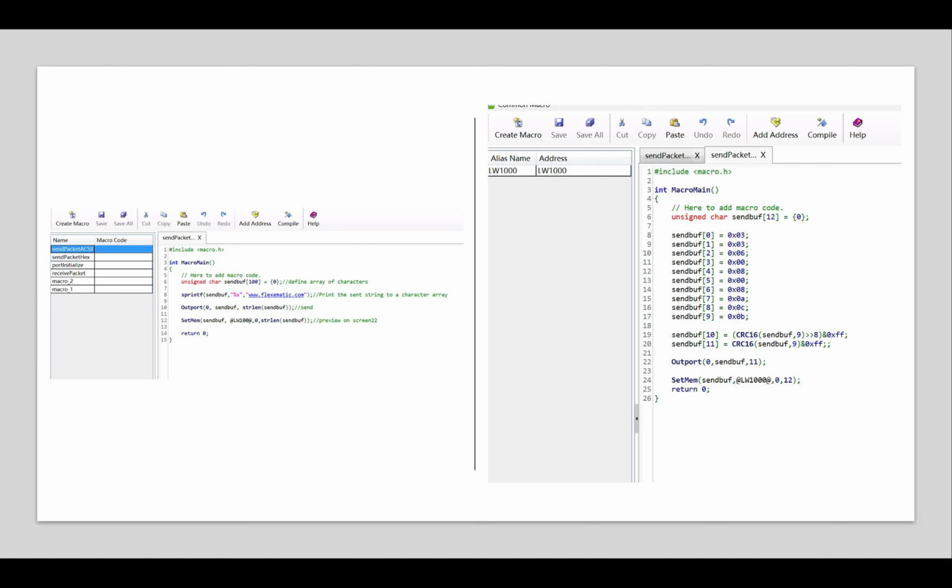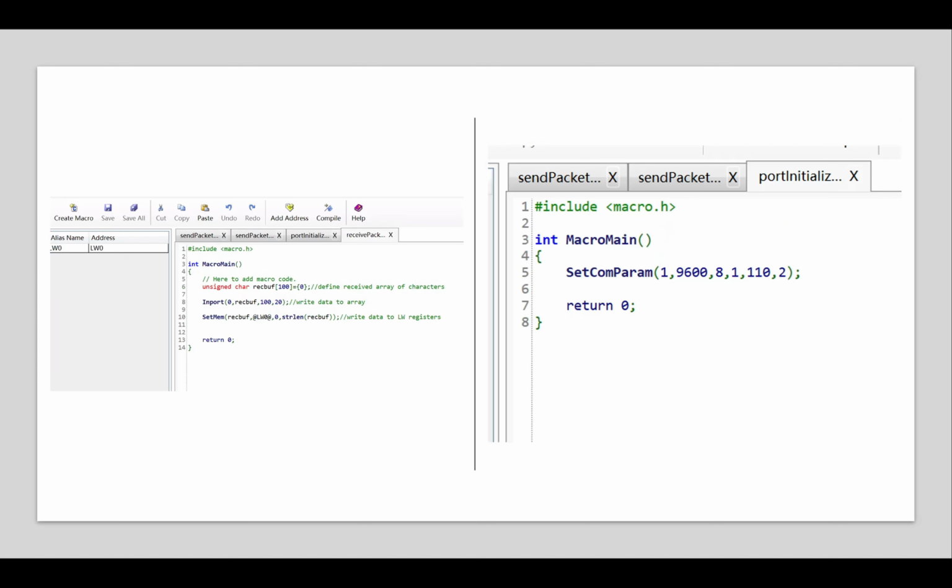It enables direct transmission and reception of HEX or ASCII messages, giving developers full control over packet formatting, e.g., headers, footers, CRC checks, timing, e.g., delays between commands, and error detection, e.g., manual CRC or checksum calculations.